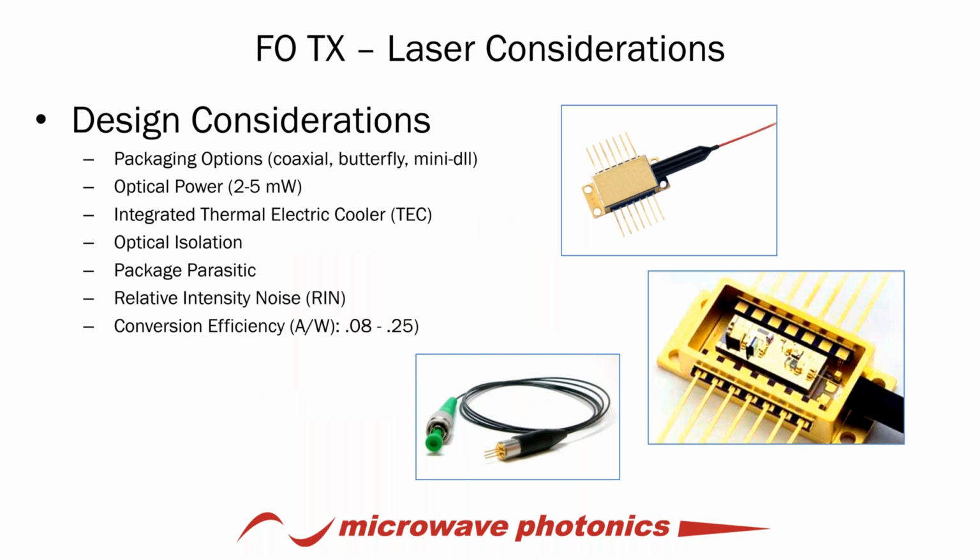There are many design considerations. Some of the basic aspects of a fiber laser go into the frequency response, the conversion efficiency, and whether there's an integrated thermoelectric cooler, and these are all different design considerations. Today, just as it was many years ago, the major contribution to noise in a fiber optic link is the laser. That is why, as we'll speak about later, defining the requirements of the system and doing proper systems engineering and requirements decomposition help to design in the best approach for the fiber optic transmitter.